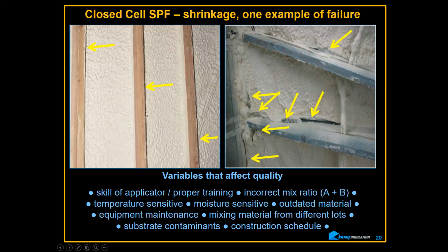So you do this on one cavity, and if it's on both sides, I can't tell because I can't see the other side of the stud. But if you do this in one cavity, you're gonna have easily a 1.5 inch hole in there. So now you got moisture problems, but you just lowered the R value maybe by half of that particular cavity. So gaps are no good. It's not considered grade 1 installation, less than 2% voids, compressions. And I don't even consider that grade 1 myself. I'm way more particular than that. But anyway, you can see the problems where inflexibility is creating a negative result.